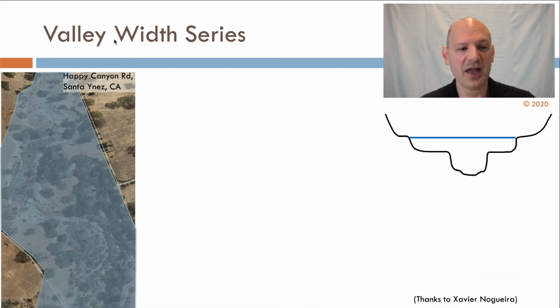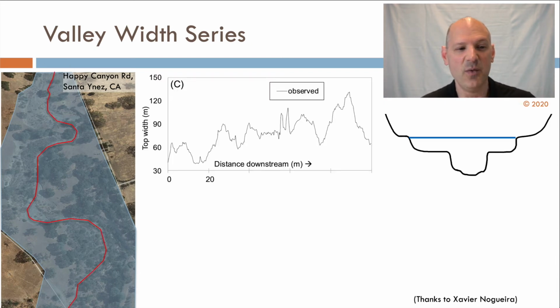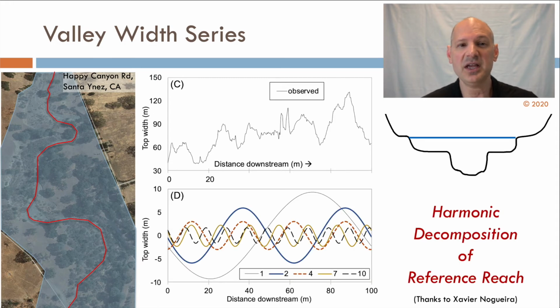Then we can go up to the flood flow. And so I've just sort of sketched out roughly, kind of like a flood pattern here. This isn't the real pattern, but it gives you a feel for it. We can then layer on again the thalweg, and we could then extract a width series going down this river, to see how the cross sections change. And we can see that here too, it's not a uniform valley. The valley gets wider or narrower as you go along. It generally is getting wider, but there's a lot of undulations here controlled by the valley width that's present.